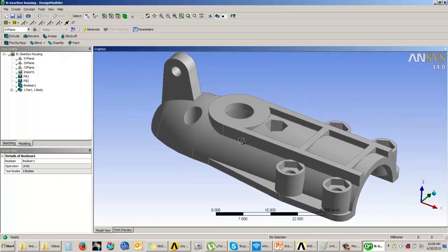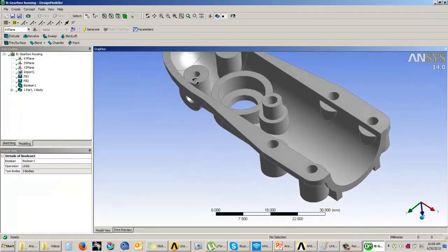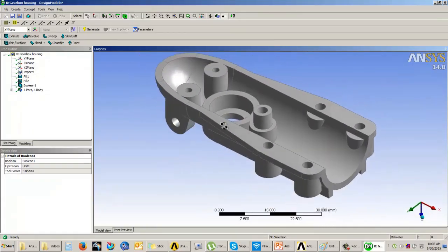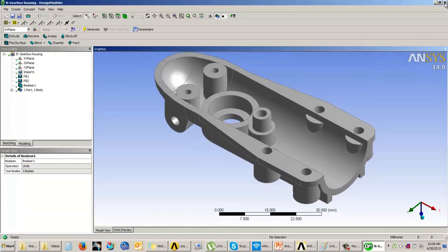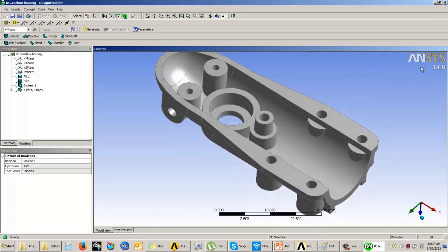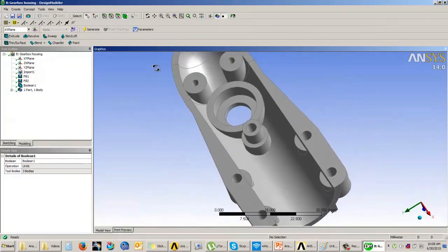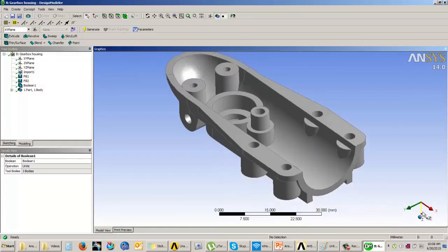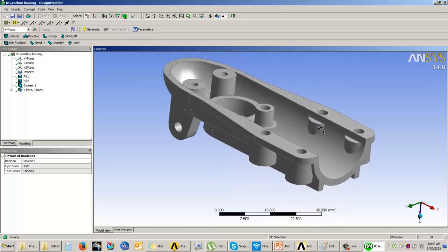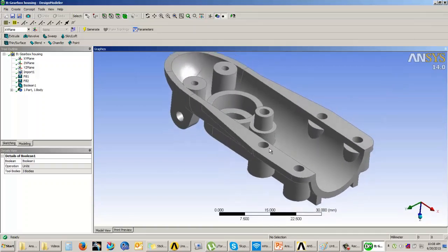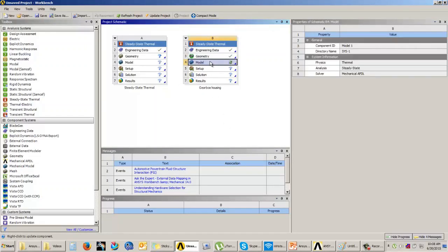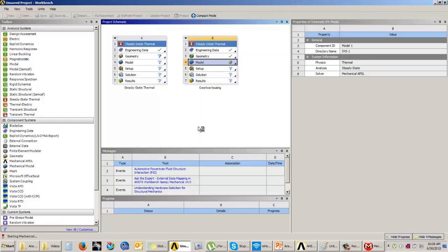After you have made all the necessary changes, let us perform the analysis. For performing the analysis, we can enter into the mechanical window. If you see, the model is exactly symmetrical, so you can also cut the material in the center over here above the ZX plane, and you can take half of the model. All these things can be done. Later on, we will come into the model cell. When you come to the model cell, first let us understand what tools are available.